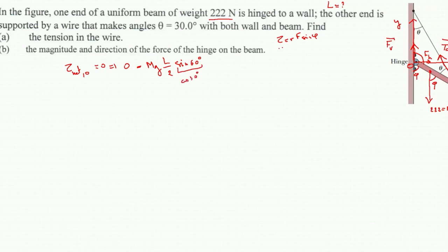So if I use, instead of this formula R F sine phi, torque is equal to moment arm times F. Well, you have to plot the moment arm. So for the moment arm, I have to first draw the line of action of the force. So the moment arm will be the distance between O and that line of action. So if this is 60 degrees, this will be 30 degrees.